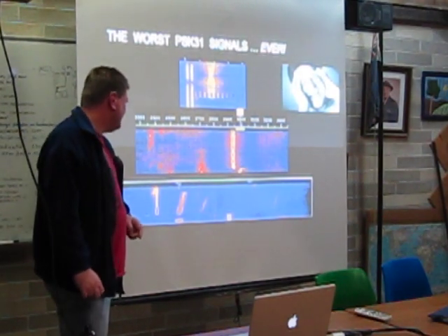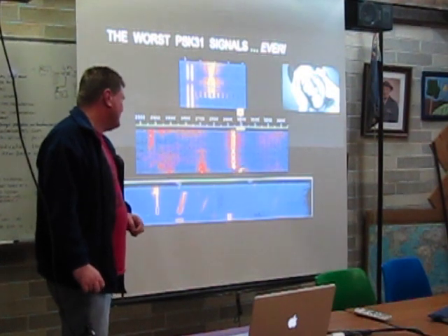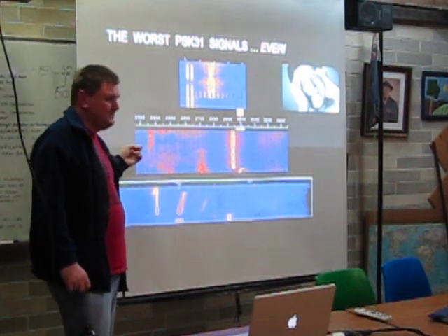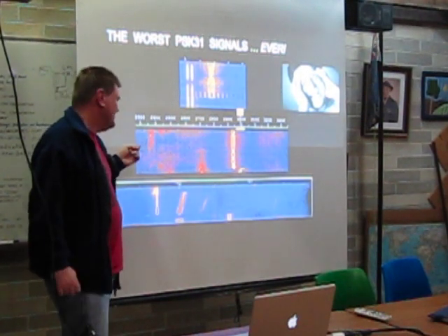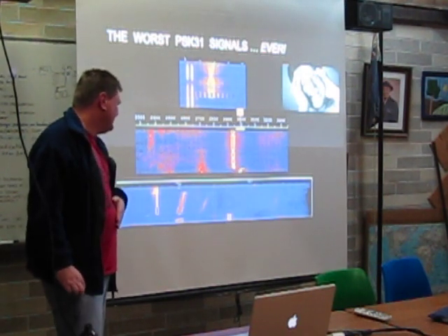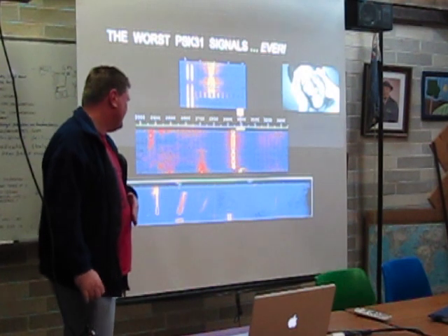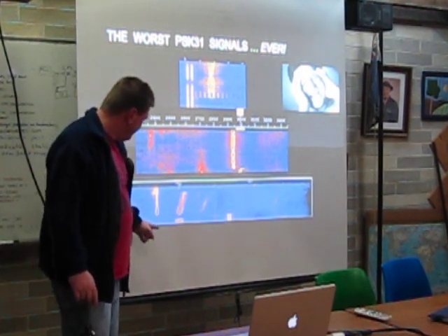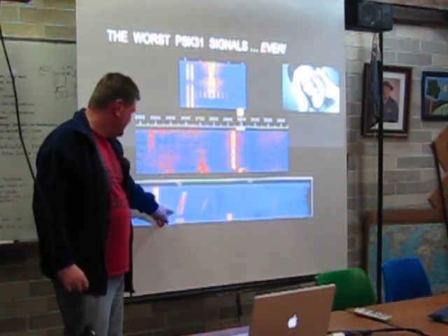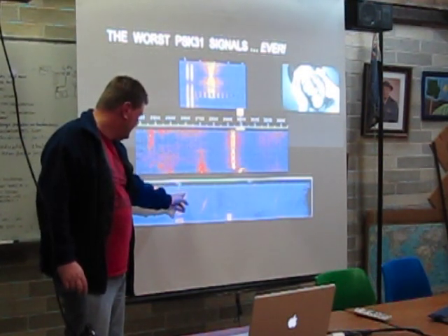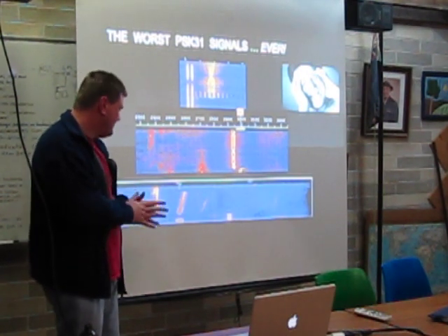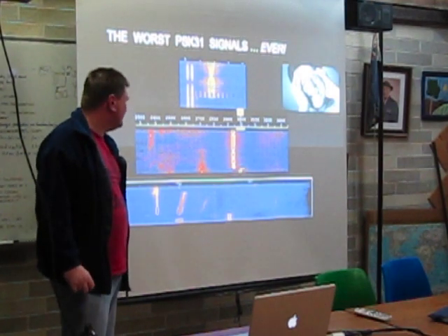So it's probably being badly overdriven at the transmitter. Could also be the receiving guy's also not got his side set up properly as well. But if the guy who's transmitting gets it wrong, then he's obviously spewing rubbish out over the bands. If your transmitter's not stable and the frequency drifts, you get this sloping thing, so that the tone starts high, and over time the tone gets slightly lower. So that means the radio is drifting. So that's also not what you want.